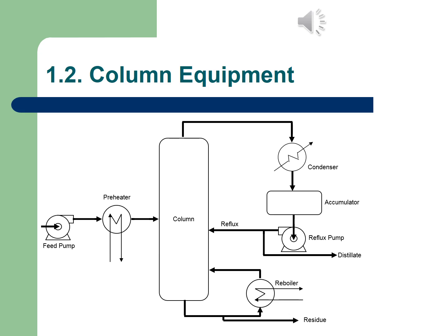Then you have a preheater. That preheater is just there to make sure that you don't now allow a colder mixture to go into the column, and it might upset the whole temperature. Okay, so you always will have that preheater. Going into the column, this is where the whole separation process will take place. And then you've got a top product and a bottom product.